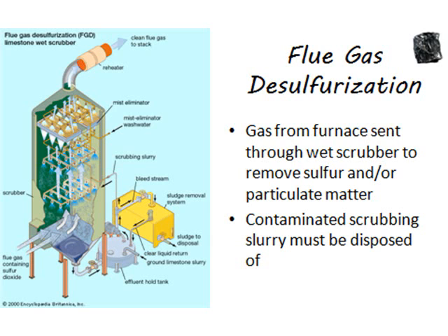They'll let the gas from the flue go through this chamber where it's basically got water blasted at it, which is supposed to help dissolve the sulfur dioxide and any sort of particles that are in the smoke. That stuff gets washed down to the bottom. It forms this slurry or sludge. Both words should bring to mind nasty, ooey gooey stuff, because that's basically what it is. And then you've got to take that and dispose of it somewhere, in a place where it's not going to cause environmental problems.